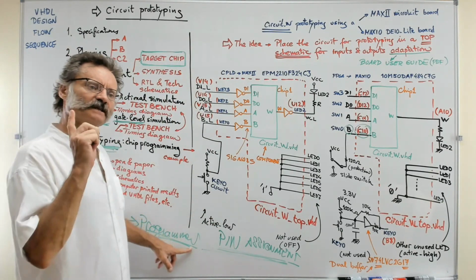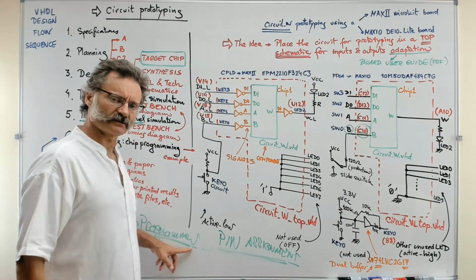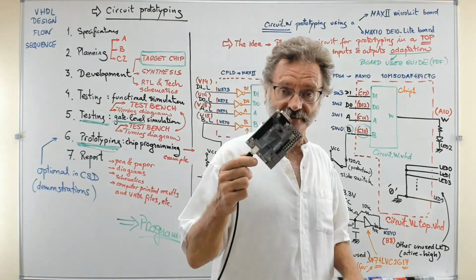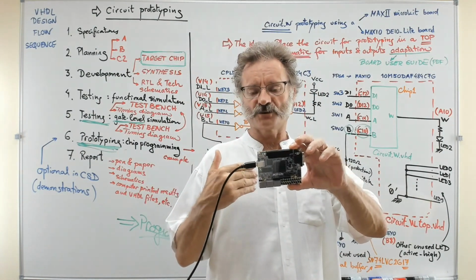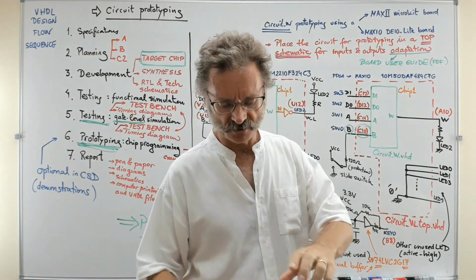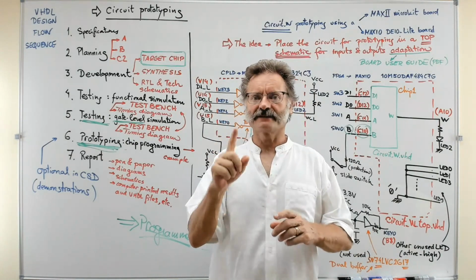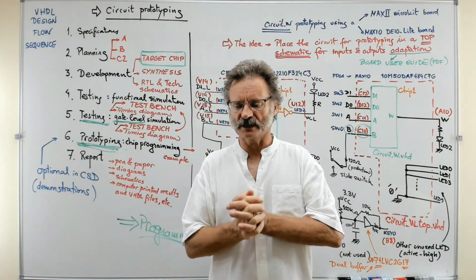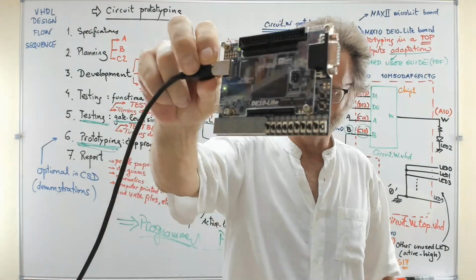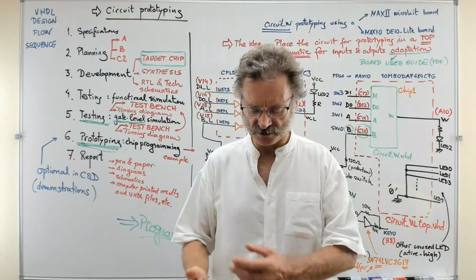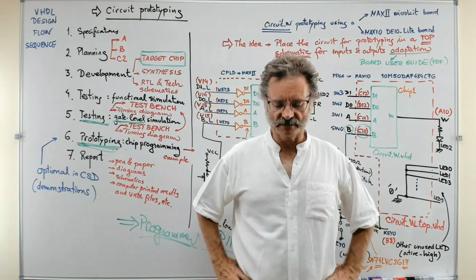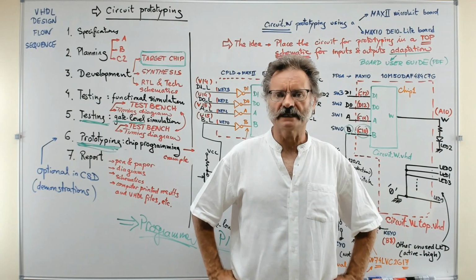So you simply open the tab of the programmer, you click the tab programmer, and you will see how the board is detected, and then you will be able to attach to the FPGA the corresponding configuration file and click download or program or start programming. In this way you will have the circuit for real, whatever it is, something as simple as just 10 gates, or something very complex, as complex as you like. Okay, that's the idea here.